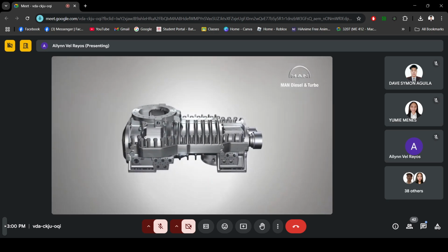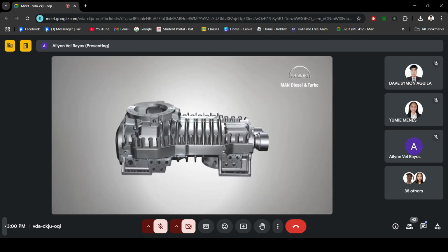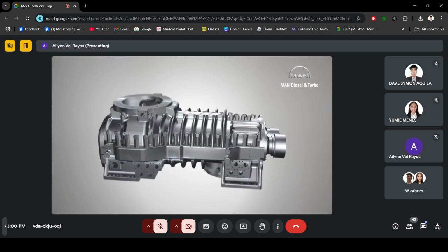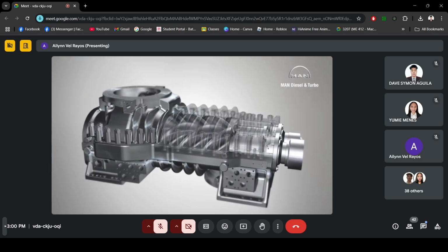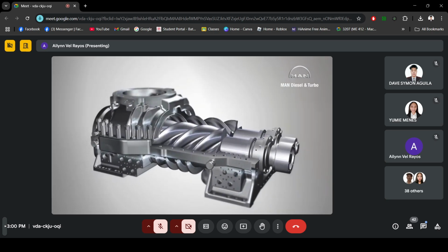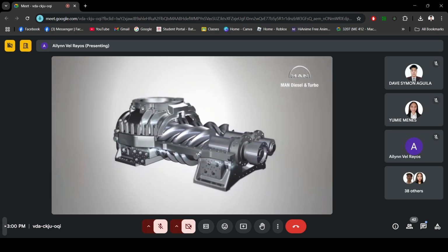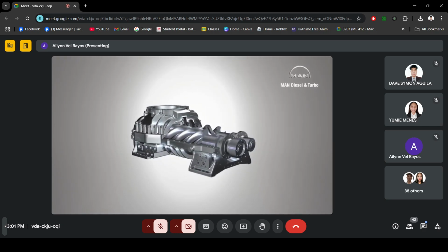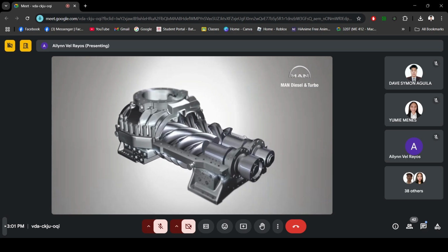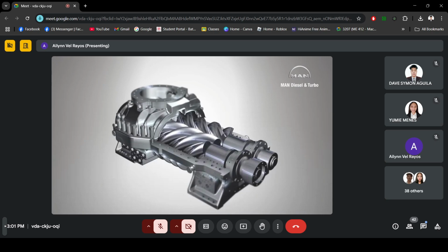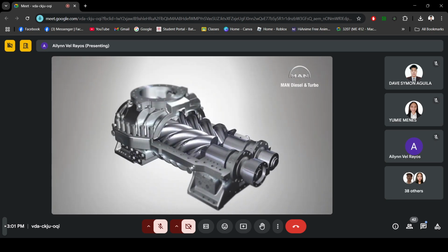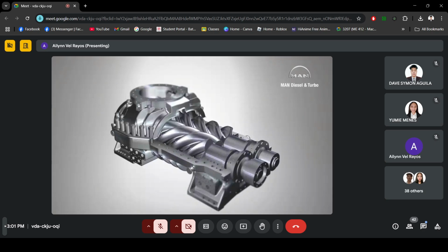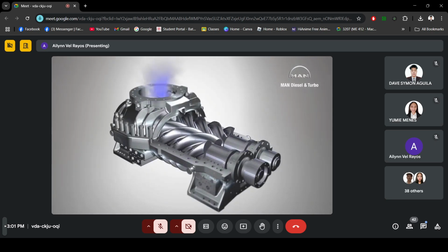All screw compressors operate according to the basic principle of a positive displacement machine, whose key element is a pair of spiral rotors. During operation, the rotors turn and the spiral teeth mesh together, forming chambers between the rotors and the casing wall. Rotation causes the chambers to move from the suction or intake side to the compression or discharge side.